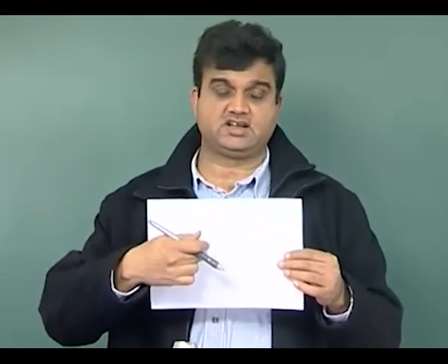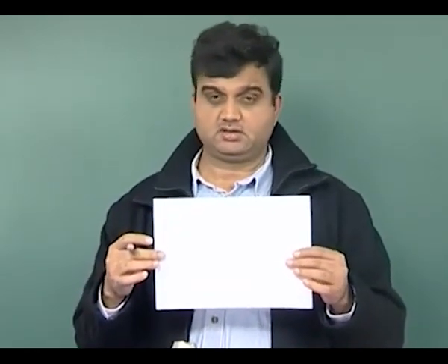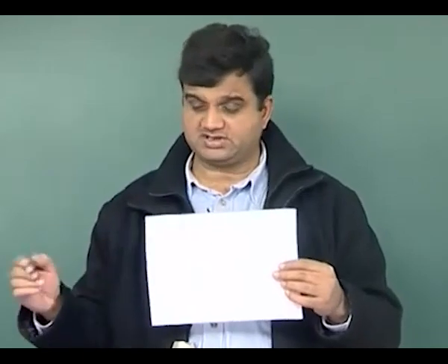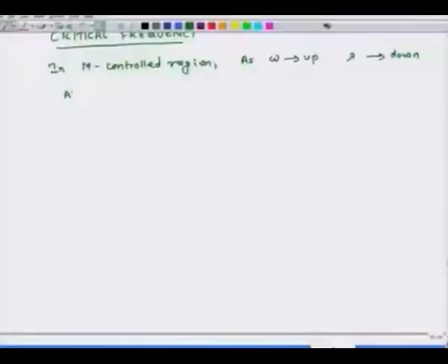Now, these bending waves also have specific frequencies and wavelengths. Typically, at low frequencies, say if I hit it at 10 hertz, lambda of sound is larger than lambda of the bending wave.